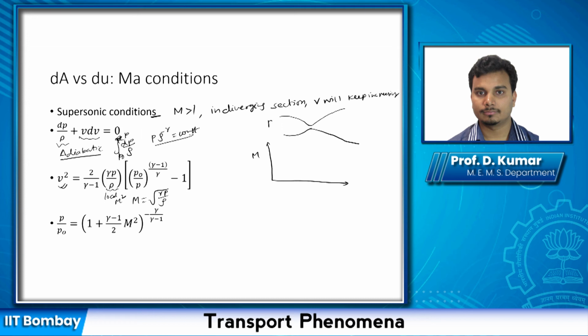Let us see. You have some initial pressure P naught here, and we have seen initially what happens if you are in the subsonic regime. You have some pressure P, which is also the local pressure, and some exit pressure PE, and you start reducing the pressure. You will initially have some subsonic velocity everywhere, as we have seen earlier. Now, if you have reached a point where you have a choked flow at the throat, then let us see what will happen.